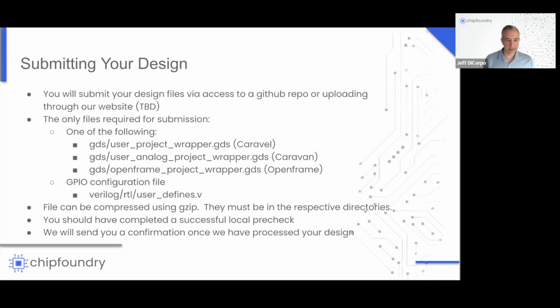And so the user defines file, if you're familiar with Caravelle, basically sets the configuration for all the I/O on the power on reset condition. So that's a design time decision in terms of how you configure the I/O. Of course, if you're familiar with Caravelle, you know that you can also go in at runtime and reconfigure those I/O using either the RISC-V processor or through a housekeeping interface available through the platform.